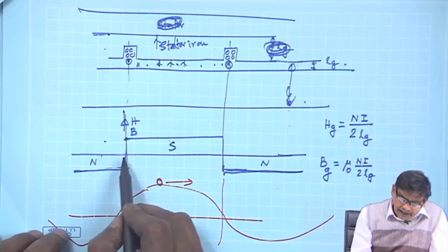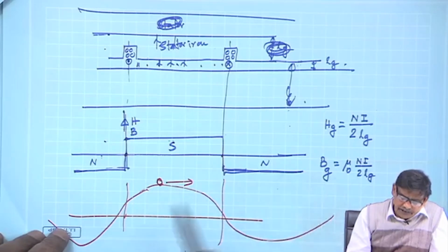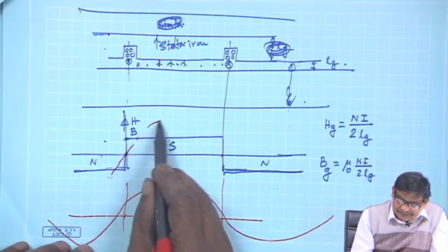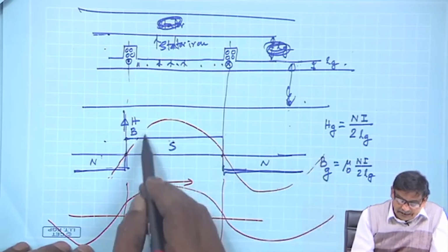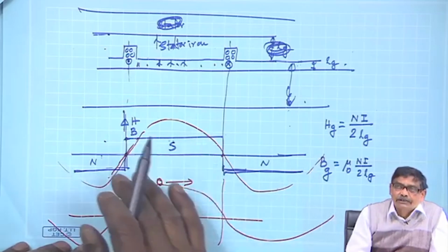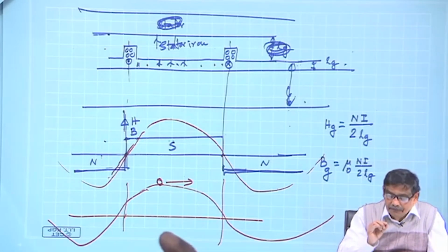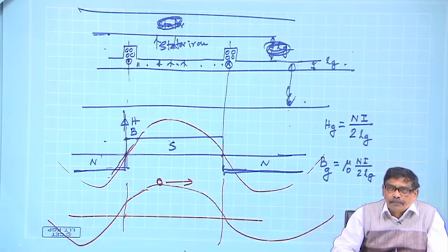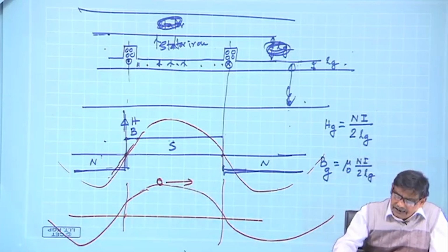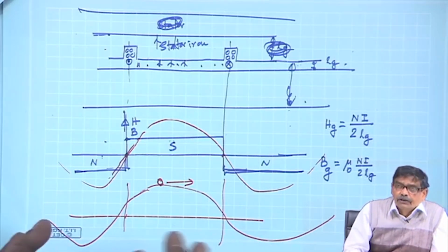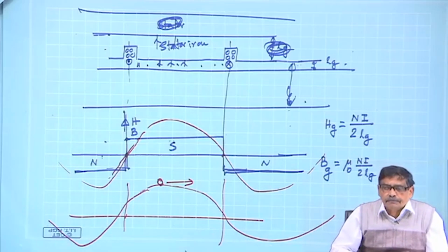For example, you know Fourier series, I can Fourier analyze this waveform and get a fundamental sinusoid with a lot of harmonics. One good thing is higher order harmonics will have reduced amplitude. So, you can say that okay, it is a square wave, but it has a strong fundamental sine wave with a lot of odd harmonics.